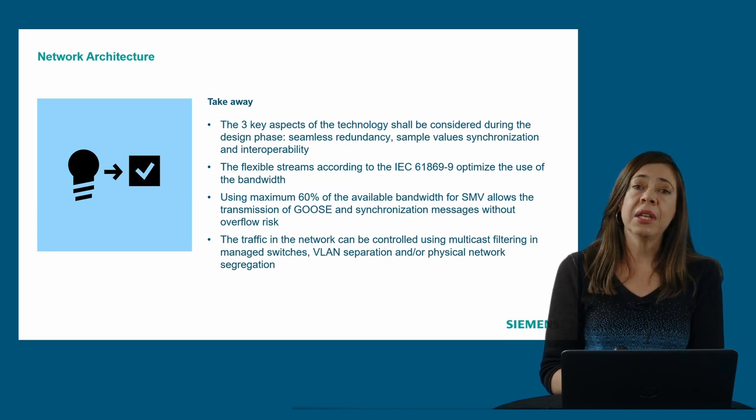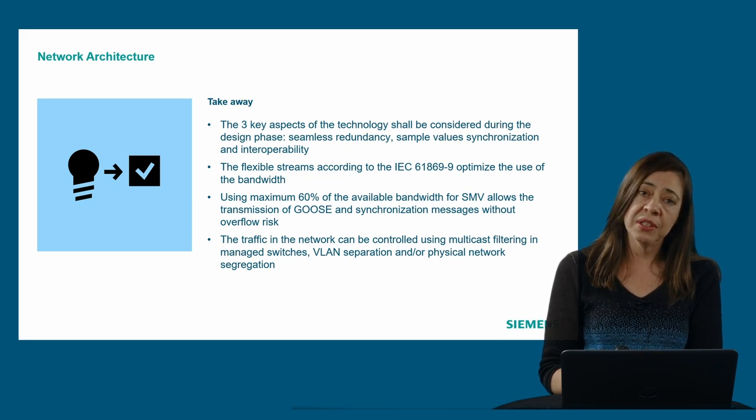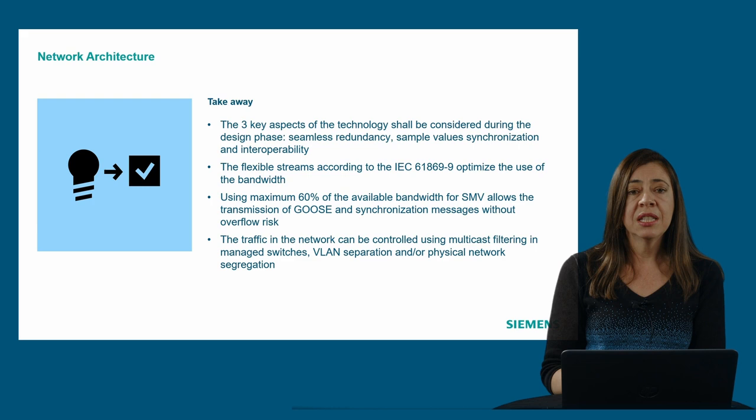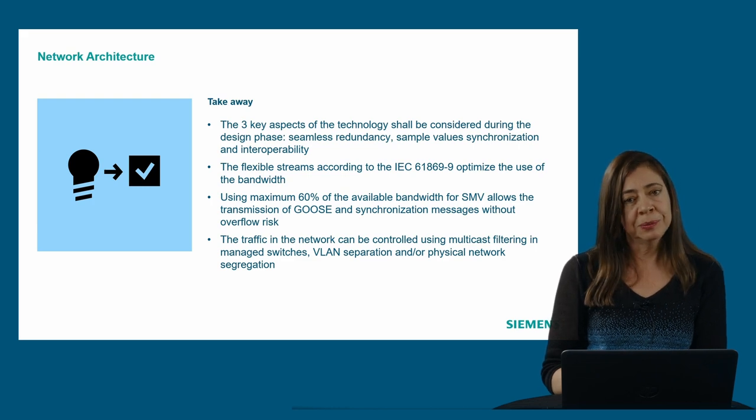And the traffic in the network can be controlled using multicast filtering in the switches, virtual LAN separation, or physical segregation in the network.